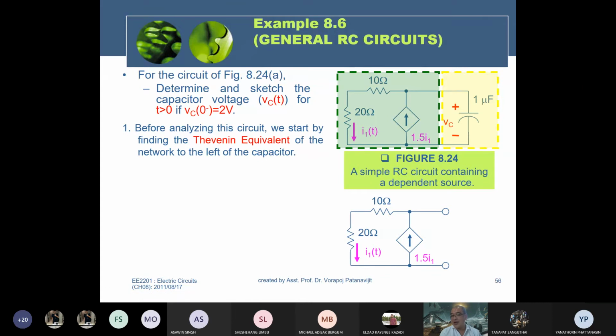You know that the Thevenin have three types. The first one has only independent sources. The second one has both sources. And the last one has only dependent sources. This is the last one, type 3. For type 3 circuits, you must add one independent source into them. In this case, you can add a current or a voltage source, depending on you.